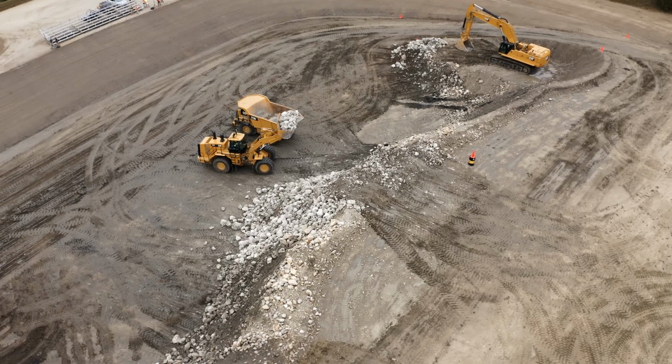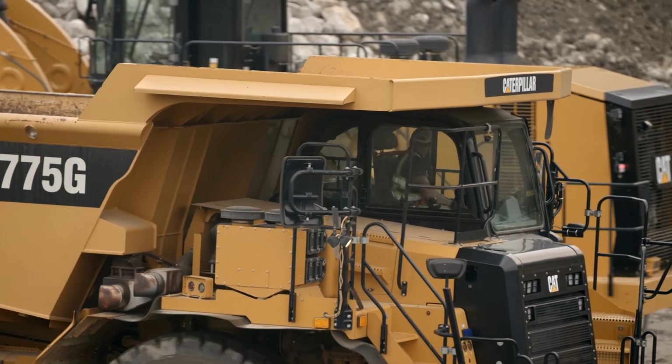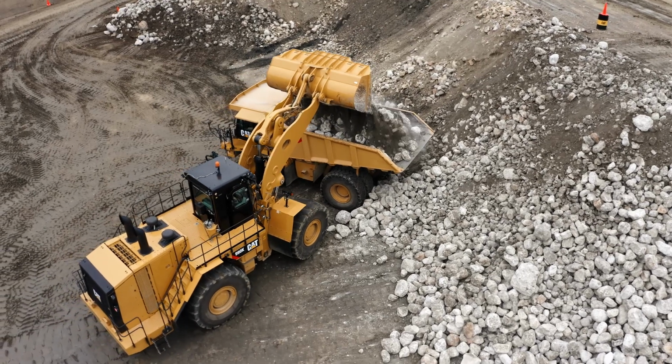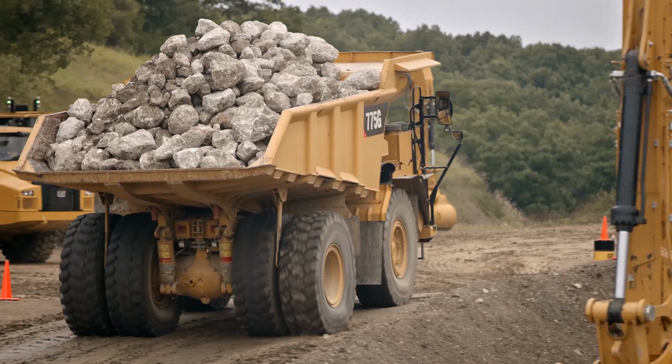We all know that if we can reduce cycle times, we improve productivity. So how do we look at that cycle time and identify some of those key inefficiencies? I'll give you a couple examples. One is identifying any pinch points in the haul road where those trucks would have another stopped event that increases the total cycle. So an intersection, for example, if there's cross traffic where the truck would have to stop at an intersection, that is going to create a stopped event that is going to increase that overall cycle time.